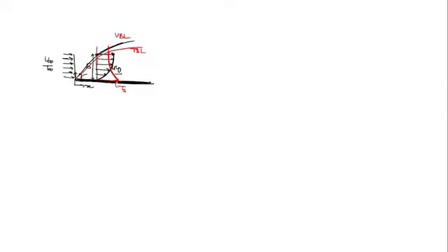And the thermal disturbance which has taken place on the wall, because only the fluid layer on the surface, the immediate layer of the fluid on the surface, will be at temperature Ts. I'm talking about the immediate layer, the red line. This is the first layer of the fluid which is just on the surface, that will be in equilibrium with the surface temperature. But any layer above that is not in direct contact, and that's why its temperature is different from Ts, and that temperature difference causes a temperature gradient, and this temperature gradient causes the heat transfer. Clear beta?